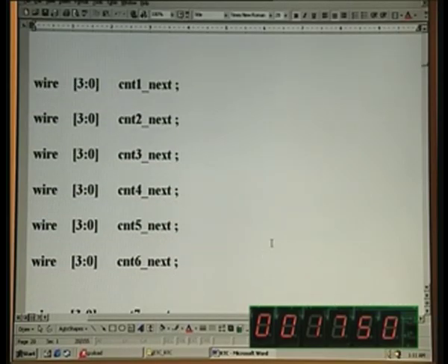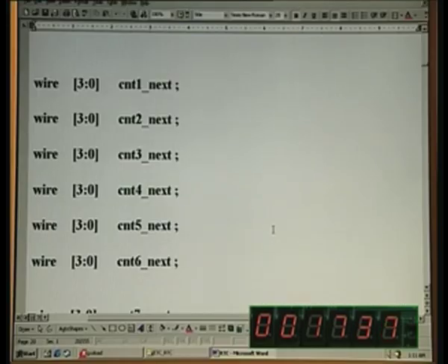And then next comes, we have been using always statements for realizing registers. A counter can be realized by that also; we have seen it in very many applications. We are going to continue the same trend even in this design. So, once again this is a very good example for counter based design. It is full of counters and nothing more, and simply by using assign statement and always statement, the entire Verilog can be contained. You can be fully RTL compliant just by using this.